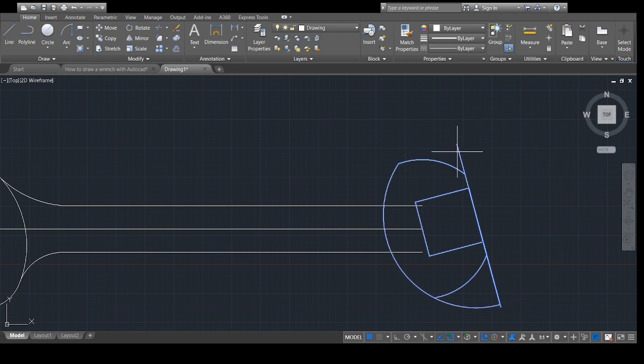and that, then escape. If you did a fillet here and put the radius as 45, select fillet, select the object, you can see that this line is being lost, and we don't want to lose that line.